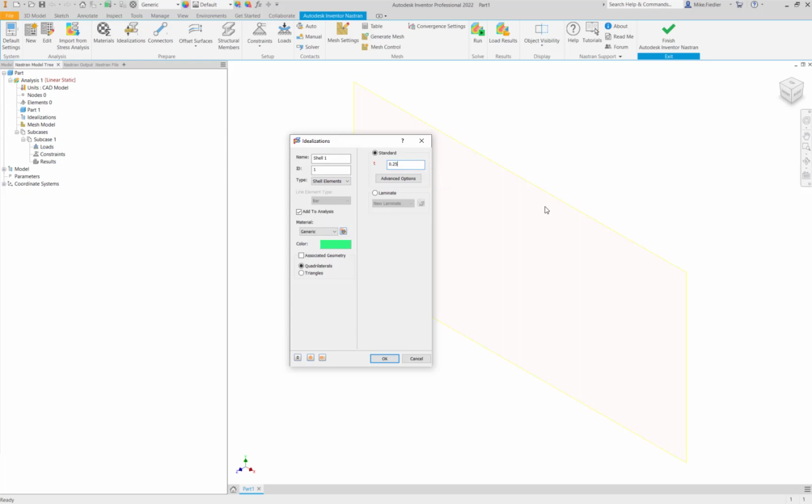If you run an analysis and you look at the stresses and you go, wow, those stresses are really, really low, my safety factor is massive, well, then you can go quickly and say, what happens if we make it out of a thinner material? Maybe save yourself and the company some costs. Sometimes the inverse happens. You analyze it, find that your stresses are quite high, and then you can take a look very quickly at what happens if we change the thickness to something a little bit more substantial.